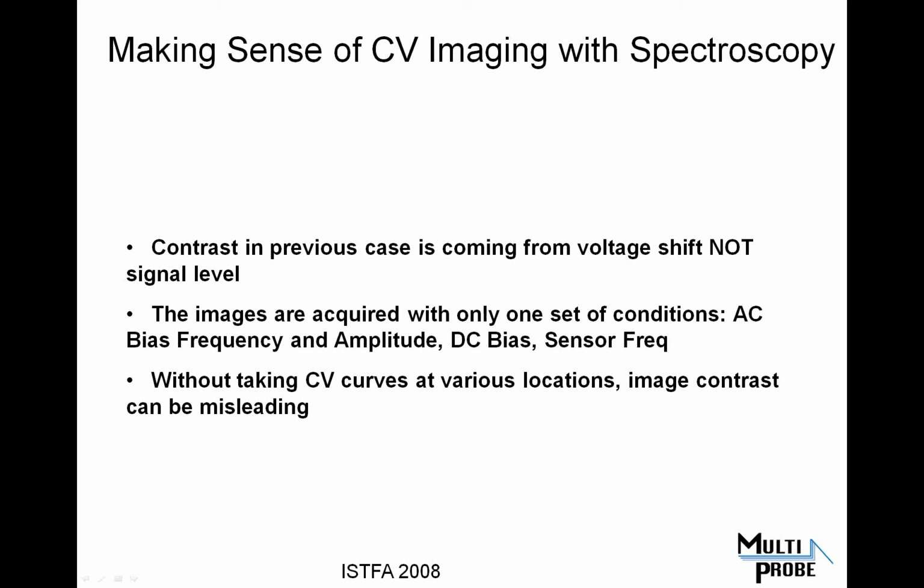And this has, I know, caused quite a lot of confusion out in the field because it's a few things to keep track of. But because now this system is relatively easy to take measurements with, and also to specify where you're taking the CV curve, where the biasing or reverse biasing effect is taking place, it becomes much easier to quantify and calibrate. What I want to say about that is that in some structures you may want to not just take an image of a structure, or just take a single point image, and place that same probe down and take a CV curve.